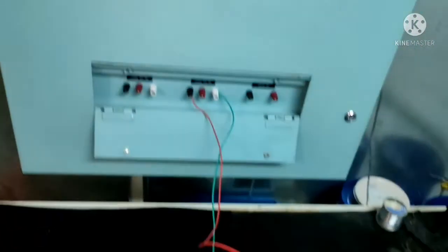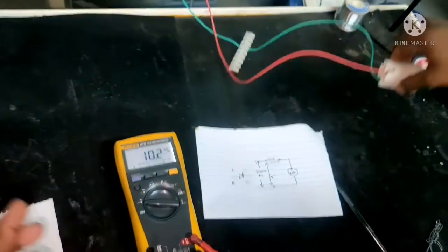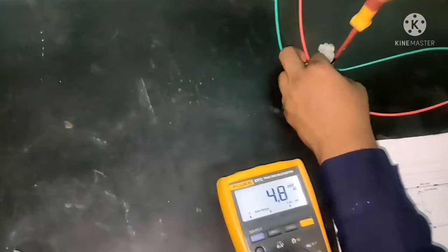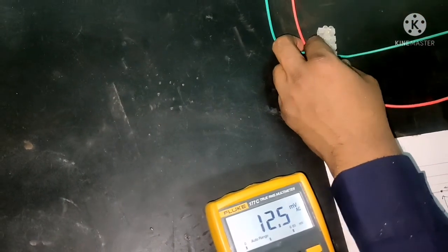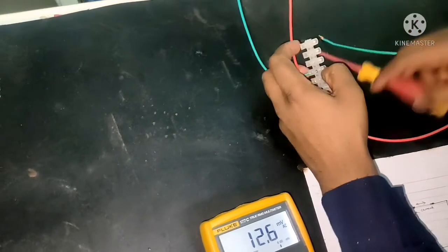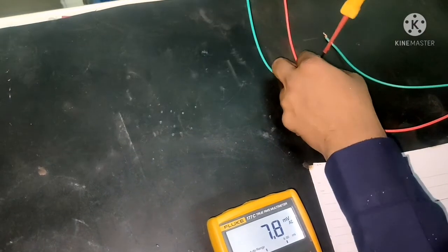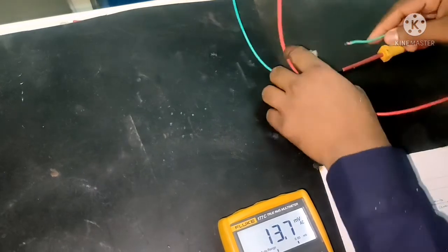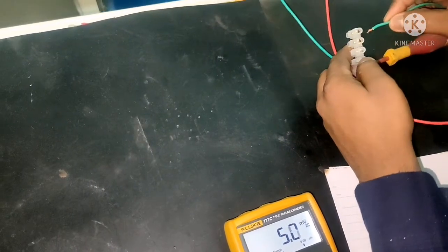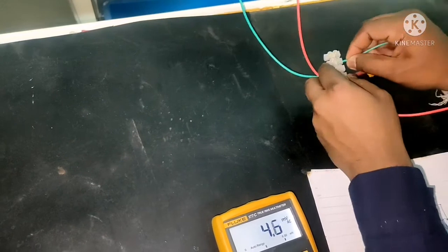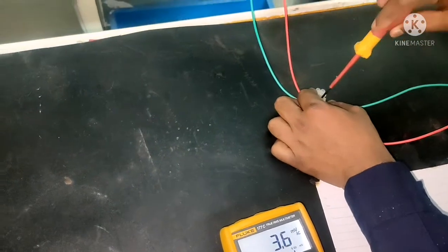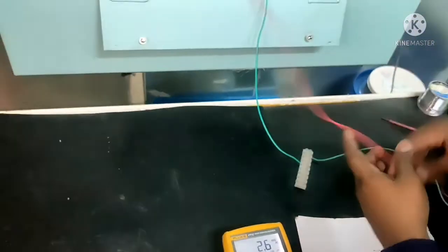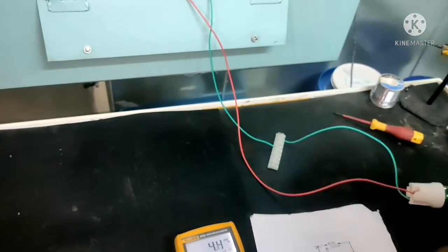Now I will switch off the breaker, and there won't be any voltage in the bulb. So now I will show how to check the current. I had connected both the wires in a single line. Now I disconnected the wire and connected it on a different terminal, because I just want to show you. I told you earlier also, we have to check current on the same line. So now I am fixing back the wire on the other end. So now I am going to check the current.